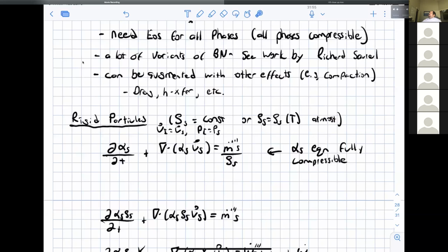And just remember that Mel Baer developed that model with high explosives in mind, and the assumptions inherent to Baer-Nunziato are really for those types of conditions. So the particles basically need to be touching, and they should be at extremely high pressure conditions like that of an explosive. In principle, you could use the Baer-Nunziato model to do fluidized beds, but because the physics of the particle collisions and all that is completely incorrect, I would suspect it would not work out very well.